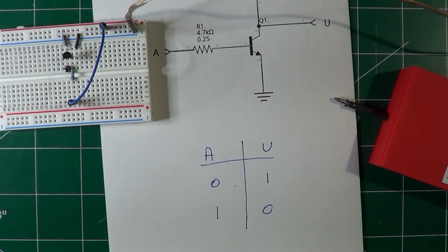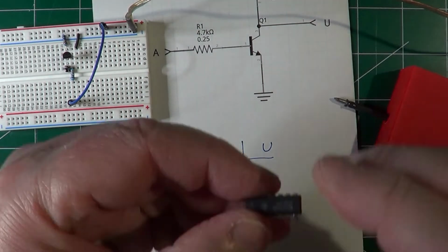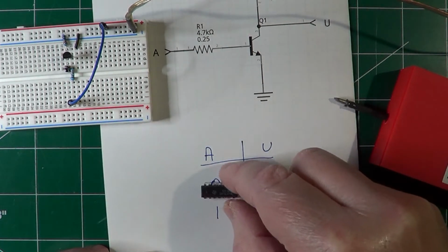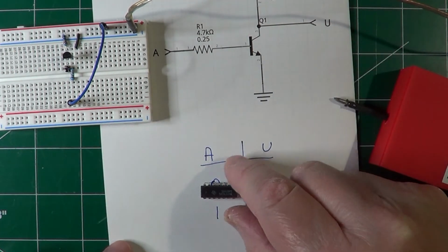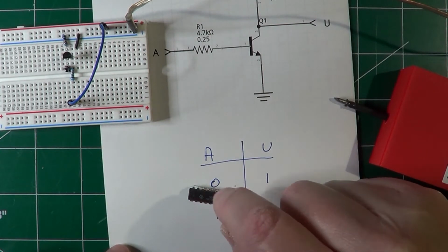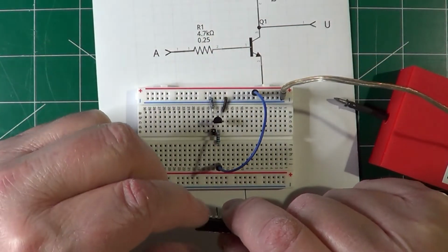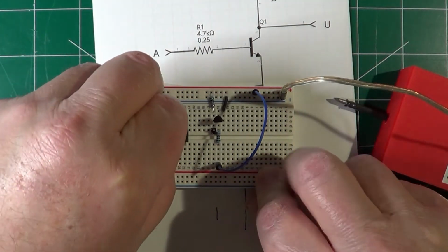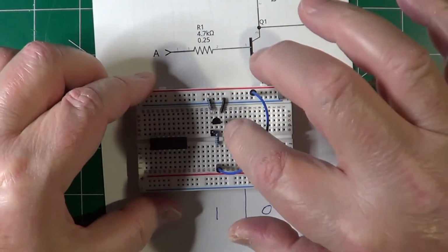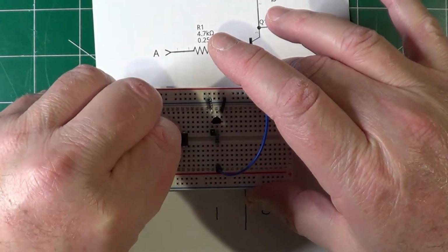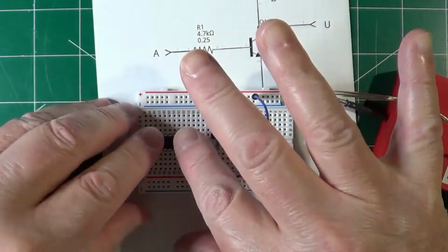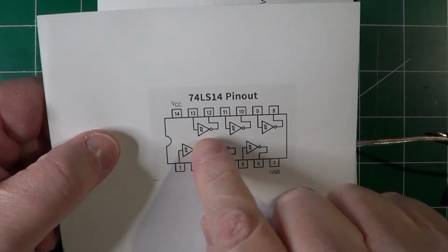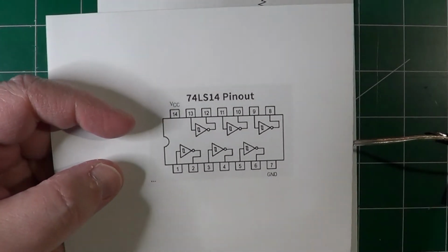Let's now take a look at another way of making a NOT gate, and that is this IC. But this IC contains not just 1, but 6 gates in it. Look at the difference in sizing of this IC with 6 gates and a single gate made out of discrete components. Let's now put the IC on the breadboard, and let's take a look at the contents of the IC, or what is called the logic diagram of it. Here is what the inside of this IC looks like logically. There are 6 inverters in it, or NOT gates, of course.